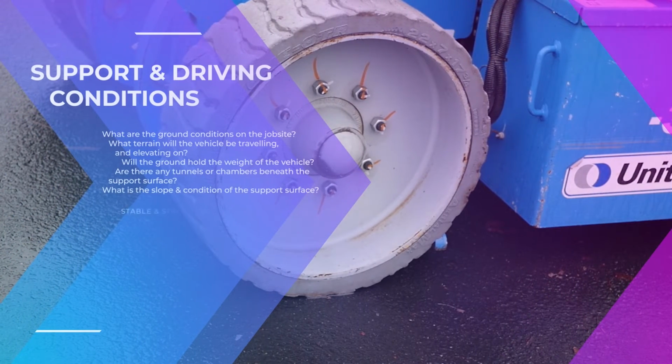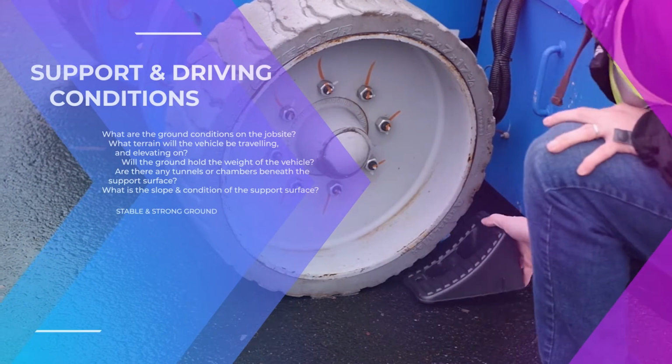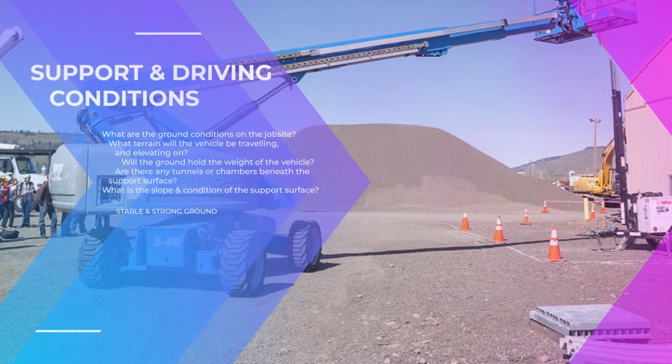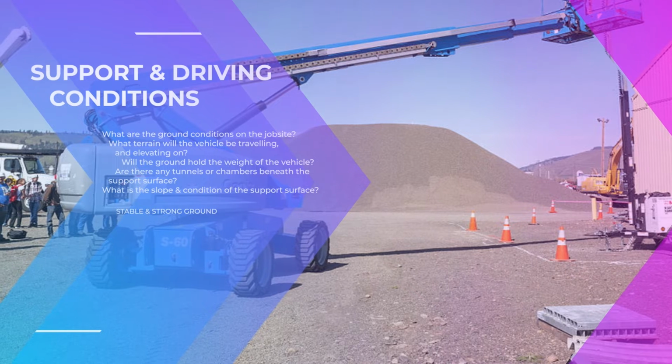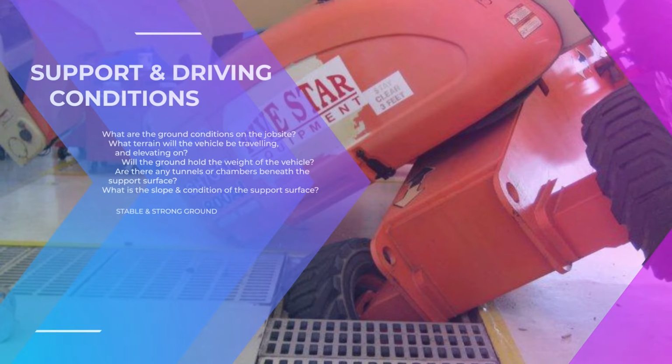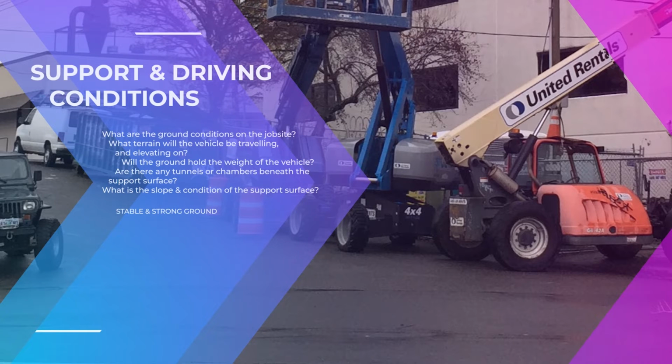Support and driving conditions. What are the ground conditions on the job site? What terrain will the machine be traveling and elevating on? Will the ground hold the weight of the vehicle? Are there any tunnels or chambers beneath the support surface? What is the slope and condition of the support surface?